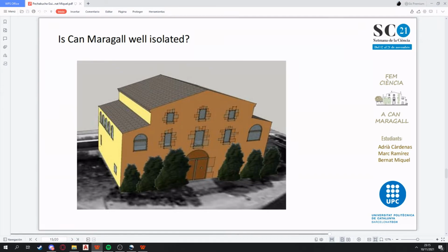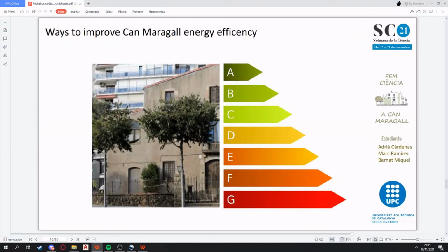It was made to be cool in summer and cold in winter, thanks to the huge walls and floor of rock and ceramic. We can reduce the heat loss through different strategies. We can use low emissivity material to avoid heat loss by radiation. We can create natural ventilation, or we can use low emissive glass in windows to reduce the demand for heating in winter.